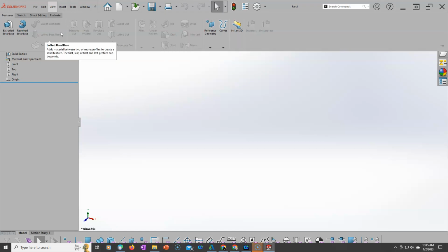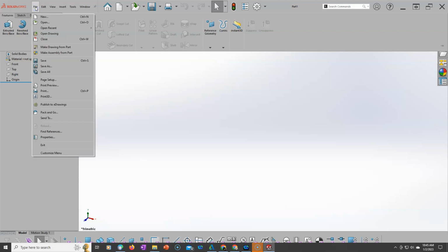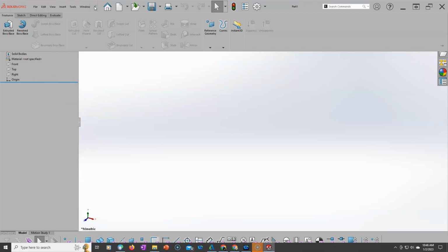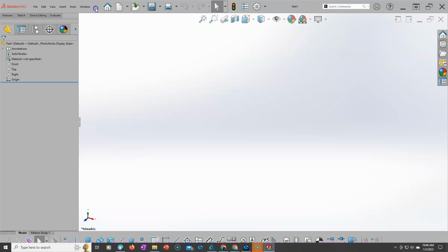this is going to change from part, assembly, drawing, we'll see different things. And sheet metal is included in the part file, so there's nothing really special about having a sheet metal active. Same with weldments. The pull downs, if the pull down is not push pinned, then it will disappear and we have the little side arrow, and if we have enough screen space, then it should not be a problem to just leave it, and then when we pick on something it expands out.